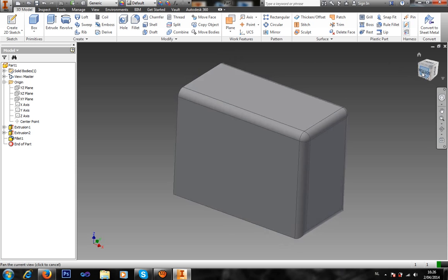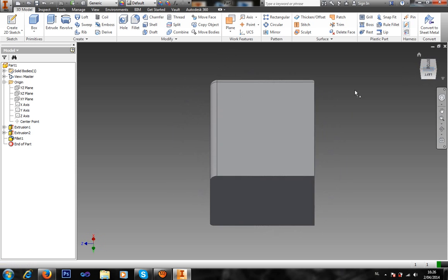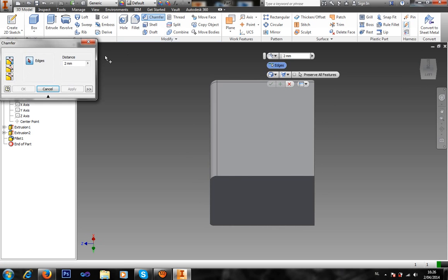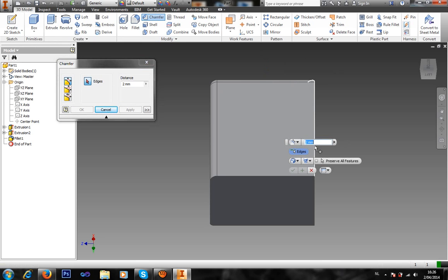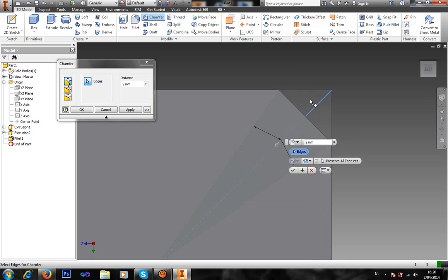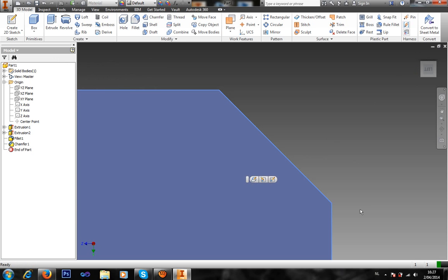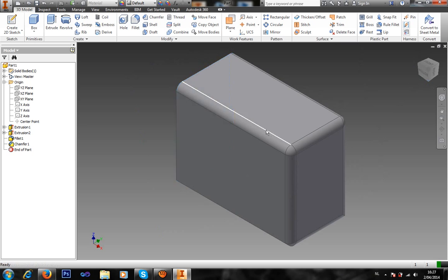Another useful thing for manipulating the outside borders of your shape is the chamfer function. Now what this does is basically, if you recall the fillet function, it does the same, except instead of rounding the edge, it picks away material at an angle by default of 45 degrees. So the same as with the fillet function, you pick a distance, say 10, and it won't do that, probably because the fillet blocks it. We're gonna pick 5, it's fair enough. Press OK, and there you go, the side has been cut off. So those are the most common things you will use.